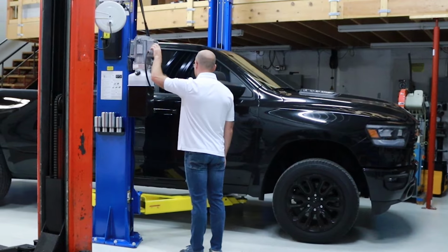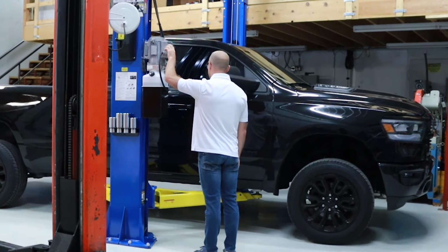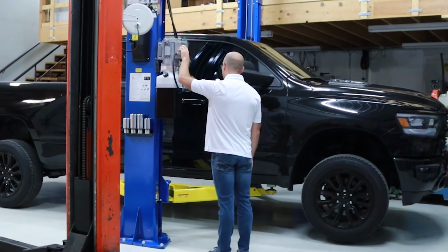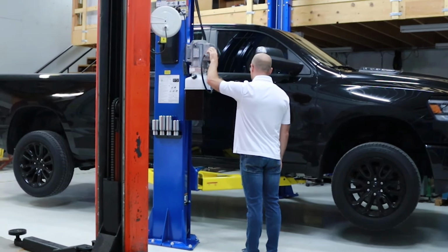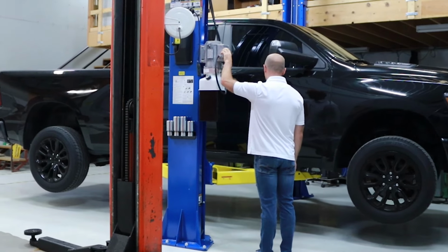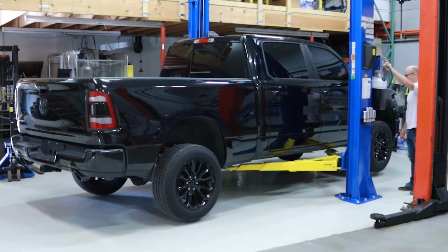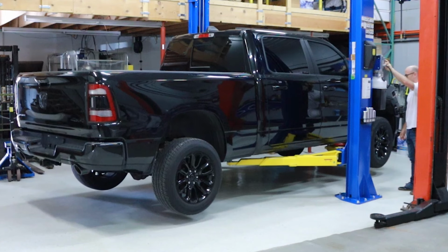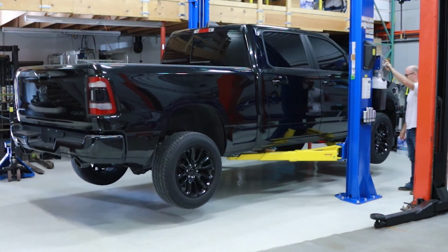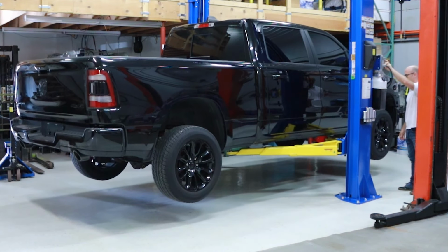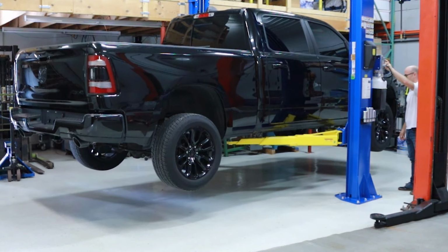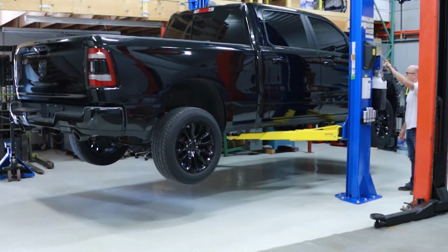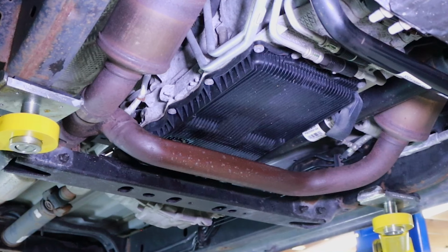To properly perform the Ram 1500 transmission fluid change, the vehicle will need to be elevated off the ground and in a level position. We recommend raising the vehicle using an SAE automotive lift. This is required in order to gain access to the bottom side of the transmission and perform the correct fluid filling and leveling procedure steps. To confirm you're lifting the vehicle correctly, you can reference your factory owner's manual for the proper vehicle lift point locations and safety procedures.